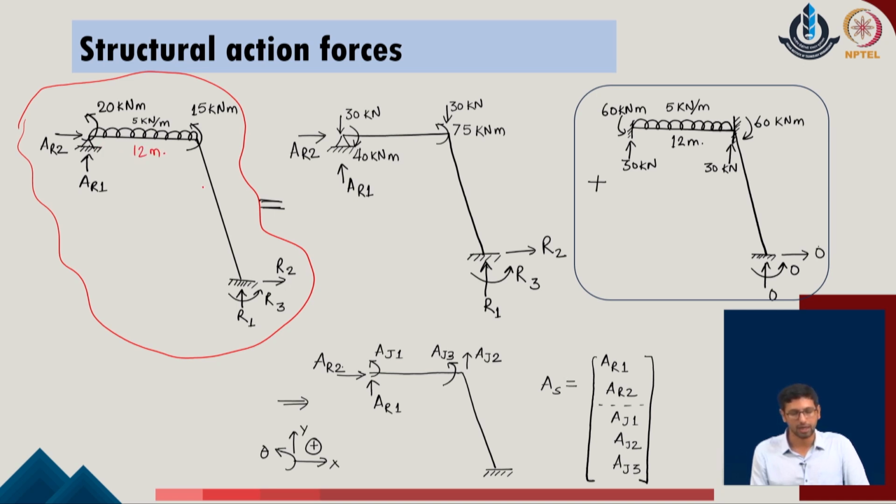So, corresponding to that, the amount of the given reaction can be identified here, which is 30 kilonewton. At the second end also it is 30 kilonewton. So, these are the two end reactions or end forces which we will get as the equivalent joint loads of the given system. We have already discussed earlier the procedure to get these equivalent joint loads.